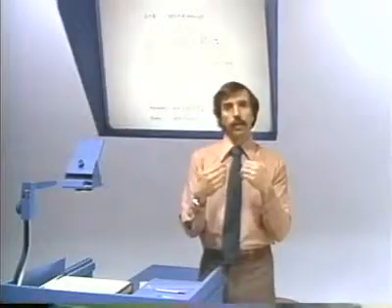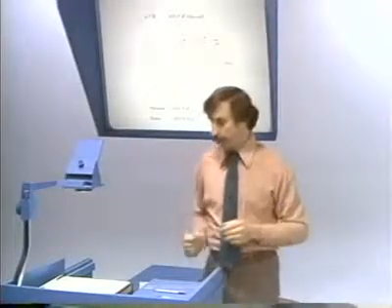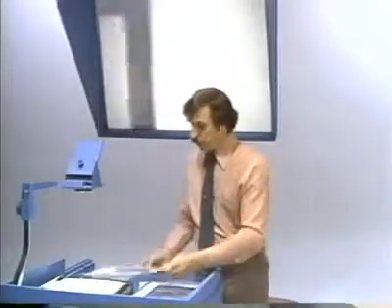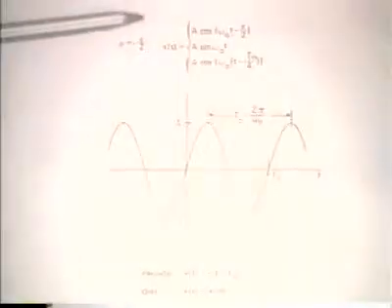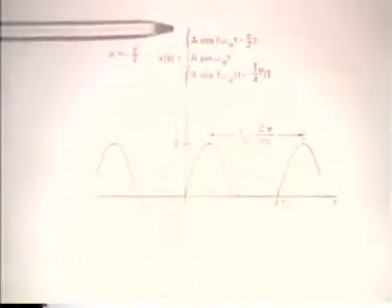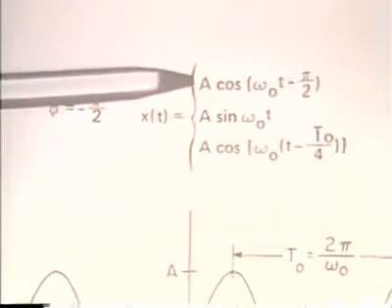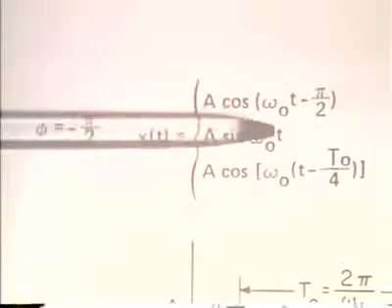Now, this corresponded to a phase shift of 0 in our original cosine expression. If instead we had chosen a phase shift of, let's say, minus pi over 2, then instead of a cosinusoidal signal, what we would generate is a sinusoid with the appropriate phase. Or, said another way, if we take our original cosine and substitute in for the phase minus pi over 2, then of course we have this mathematical expression. Using just straightforward trigonometric identities, we can express that alternately as sine omega 0 t.